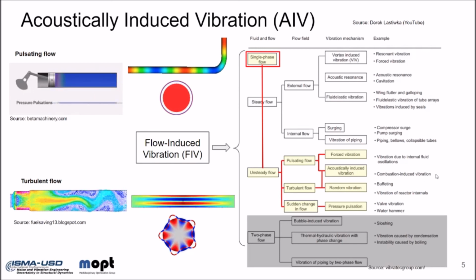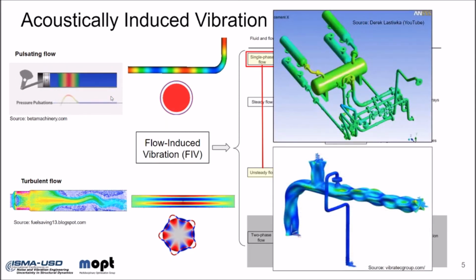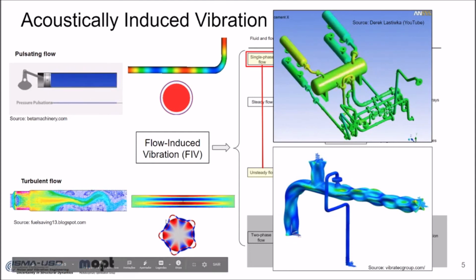Considering gas, a pulsating flow can be related to suction and discharge of compressor systems, where the energy is concentrated at the first harmonics of the rotation frequency. In this case, in general, internal longitudinal acoustic modes are activated, causing the pulsation of the pipe wall, which leads to equivalent loads on elbows and so on. And the turbulent flow can be related to turbulences and vortices caused at discontinuities like valves, expansions, etc., depending on the velocity of the flow. In this case, internal higher order acoustic modes can be activated, causing higher order modes of the pipe wall.